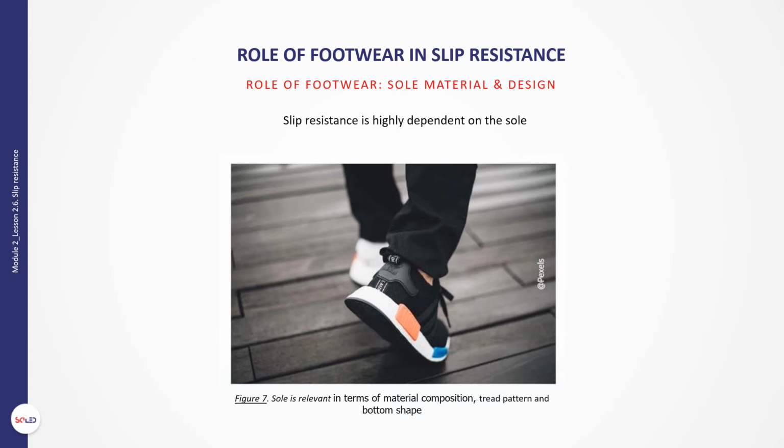In this case, tread patterns should not become clogged with any waste or debris on the floor. If soles do clog up, redesign the sole, for example with a wider space between the cleats and a deeper tread pattern. Note that slip resistance properties can change with wear. For example, some soles can deteriorate with wear, especially when the cleats become worn down. Therefore, it is essential to promote adequate sole abrasion resistance.